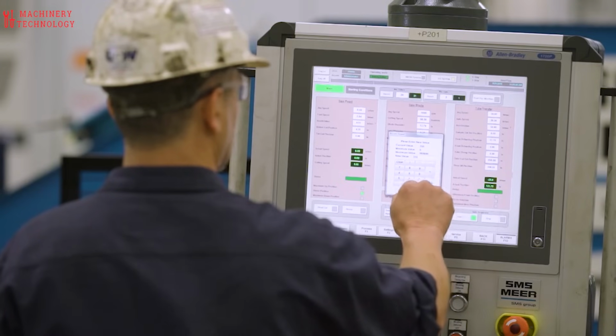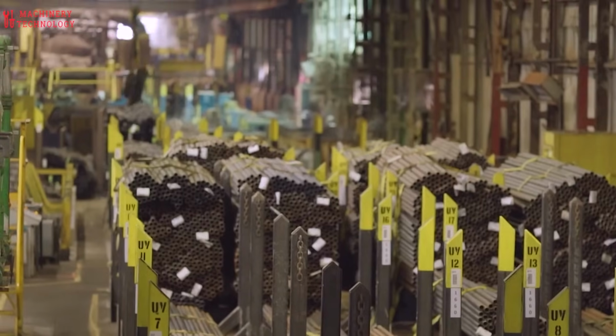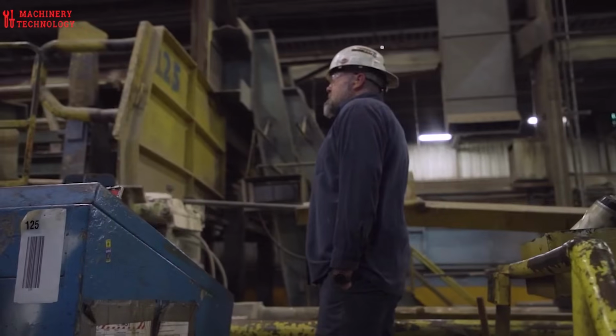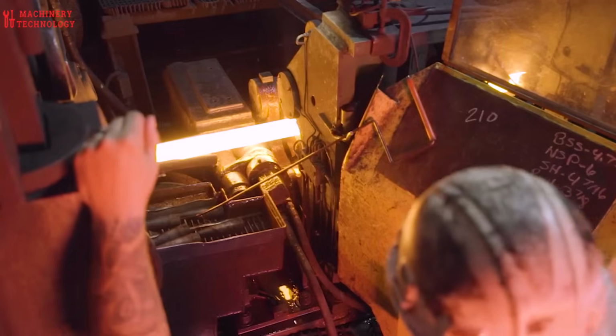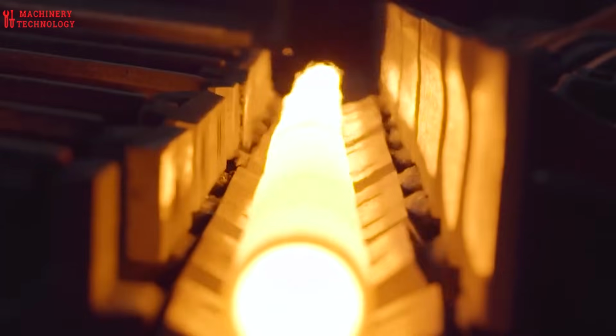The manufacturing process for DOM round steel tubing begins with coils of steel, which are slit to the proper width for the desired tube size. The strip is cold formed and passed through an electric resistance welder, which joins the edges together under pressure to complete the tubular shape. After testing the weld's integrity, the tubing is cut to length for further processing.